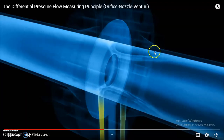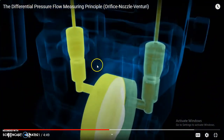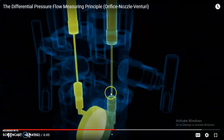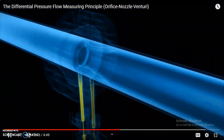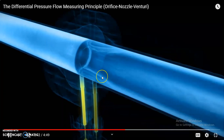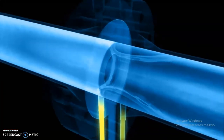You can see in the convergence and the divergence how the velocity and the pressure change. Based on that, your pressure difference can be measured using the U-tube manometer. The difference can be changed according to the pressure sensor connected downward. So this is how your orifice meter works from an industrial point of view.